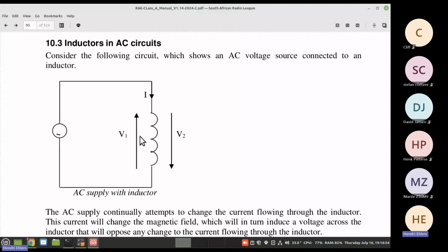Some of the guys that do the research with the baluns, you do the same balun on a couple of different cores, and then they see which one is most effective and most efficient. You'll find them in switch mode power supplies, because the switch mode power supply operates in the ideal frequency for those ferrite cores.